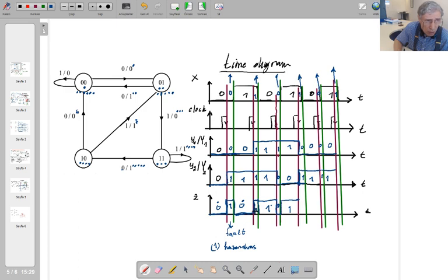If it is not very critical for you to run the circuit, you might say this is a false output, but it is not hazardous. This zero is different because this zero is in between two ones. Therefore, it is a hazardous zero. So you could continue on like that.